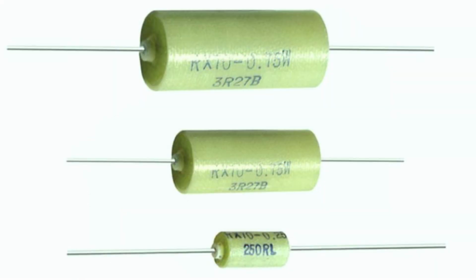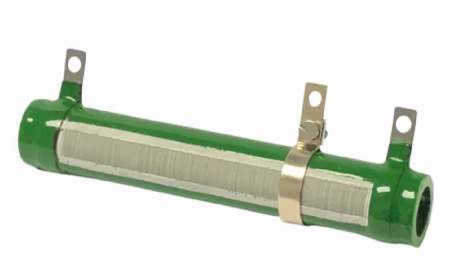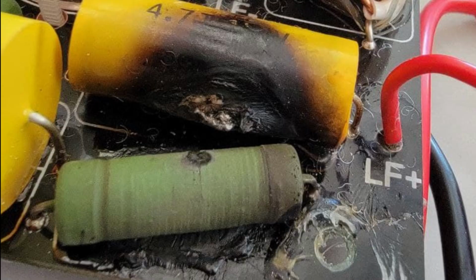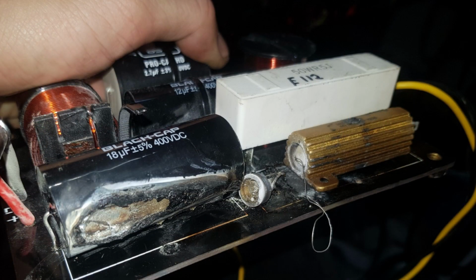Another type of resistor, called a wirewound resistor, is made by winding a thin metal alloy wire, nichrome, or similar wire onto an insulating ceramic former in the form of a spiral helix similar to the film resistor above. They are also able to handle much higher electrical currents than other resistors of the same ohmic value with power ratings in excess of 300 watts. These high-power resistors are molded or pressed into an aluminum heat sink body with fins attached to increase their overall surface area to promote heat loss and cooling.